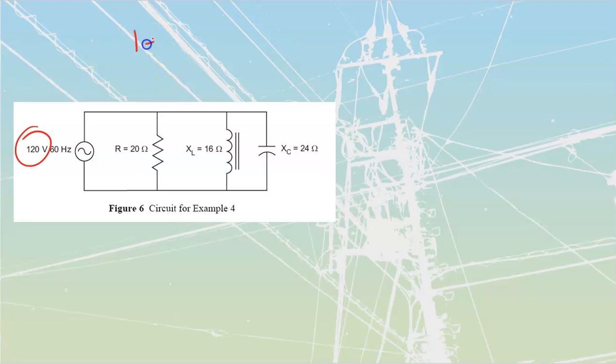We're going to say I is equal to E over R. Well, we're not going to say that. George Ohm said that. But we're going to use this formula over here: 120 volts over my resistance. So for the first one, it's going to be 120 divided by 20, which we don't need a calculator for. We should find that we have a current of 6 amps.